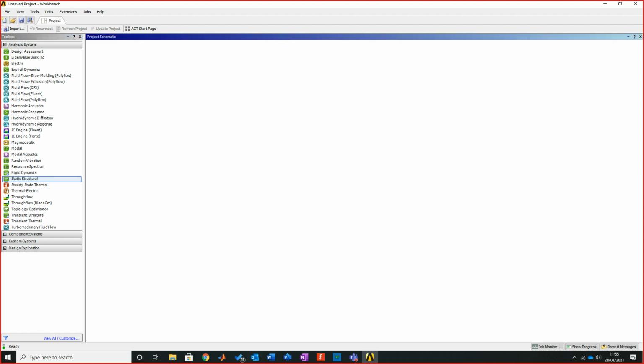Right, so what I'm going to do is drag and drop. Left click, get my finger on the left click, drag across, and drop it into, you see where you've got the construction lines. If I drag it in, you see there it says create standalone system. Keep your finger on that left click, let go and drop. Now what we've got is the overall setup for our all important structural analysis.